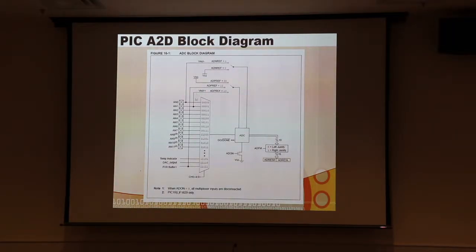And then your positive reference comes in on AN1. So we generally don't use these external reference pins. You could use them, but you have to connect them after you program the part. So you program the part, then you would put the chip on the board or solder these references into place, or you would put jumpers on or something.